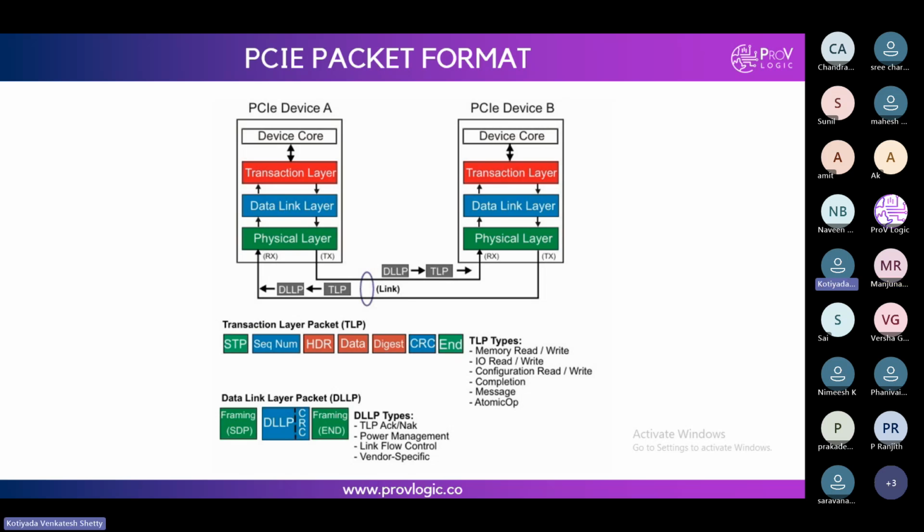So after that, the job of the data link layer is done. Then they need the actual data transfer. See, in PCI, the data transfer happens in 5 types of packets. For suppose if you want to send data to the system memory, we use the memory transfers, memory read and write. And IO: in the present generation, we are not using any IO packets.